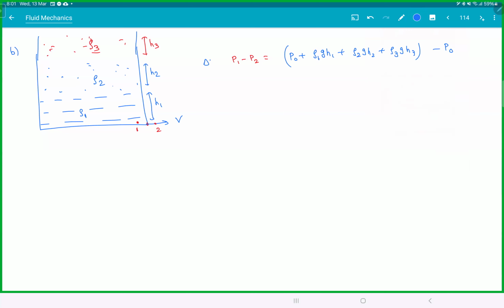Again, a delta P. So what is the formula? Root over 2 times delta P by rho. Which rho will you take? The liquid which is coming out. So root over 2 delta P by rho 1. You're getting this? Because with Bernoulli, you're applying it for a given liquid, isn't it?